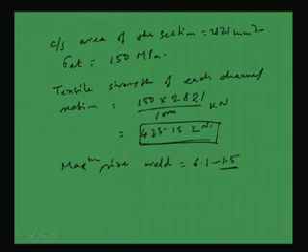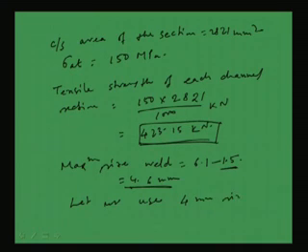So here it is coming around 4.6 mm, right. Now the minimum size we know is 4 mm. So as the maximum size is coming 4.6 mm, let us use, say, a 4 mm size weld, right. So the size of the weld has been fixed now.